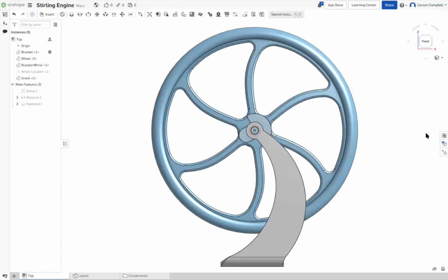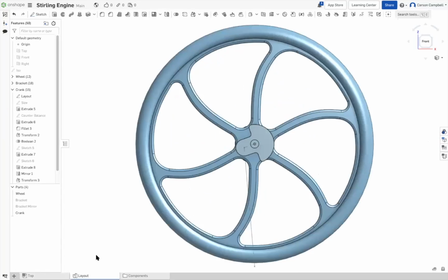Okay, and let's go back to layout. To be honest with you, I would not rotate the counterbalance in the layout because I've got two things going on. The sketch becomes kind of a mess. I would prefer to have drawn the counterbalance in either a vertical or a horizontal position, and it starts to rotate when it's in the assembly.